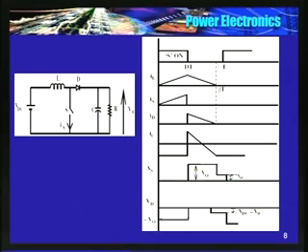Cathode potential is V0 with respect to the ground. What about the anode potential? Anode potential is VDC with respect to ground, isn't it? Just now I said that with no current here, this point is the same as this, so VDC appears across S. Now VDC is the potential of the anode of the diode with respect to the ground, or the negative DC bus.